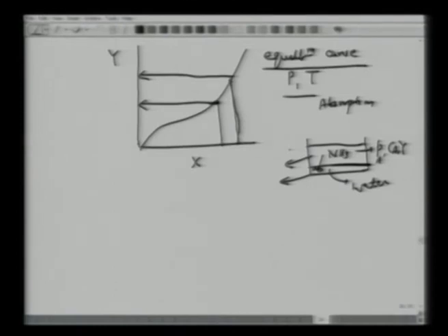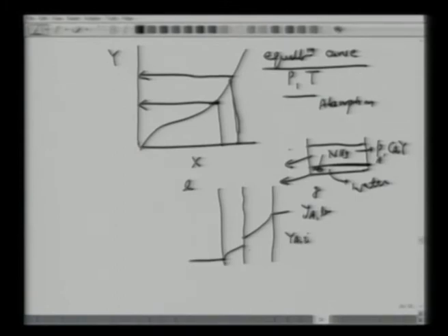Okay, and we wrote that there is an interface, two resistances here, and the concentration drops like this to this. So let's use the nomenclature. Maybe this is the gas side, this is the liquid side, A is the diffusing species, we have YAB, the bulk concentration, we have YAI, we have XAI, and we have XAB. So two phases here, liquid and gas. And we write the expressions for NA once more.